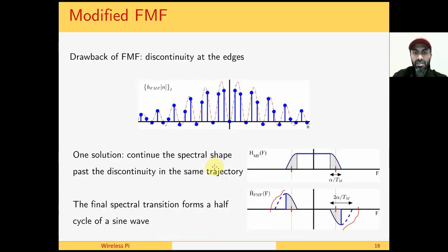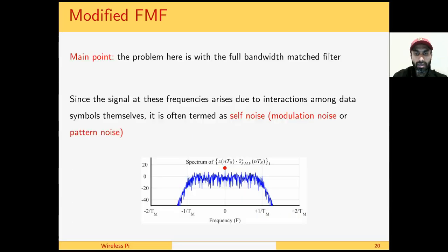One problem here is that the convolution of two terms like these involves the whole bandwidth of this match filter output. So imagine this shape rolling over this spectrum. Even in this region, when we don't need any output, even then there will be an overlap, and we have signal at these frequencies which, due to this convolution, could be avoided.